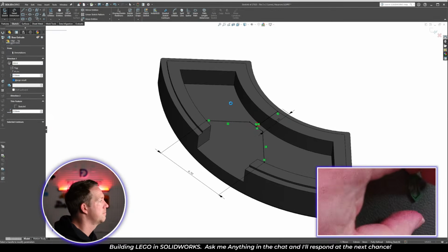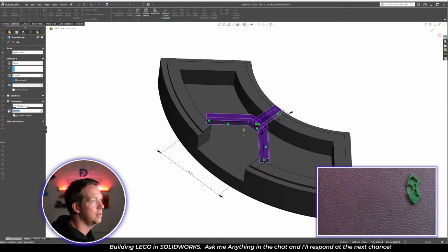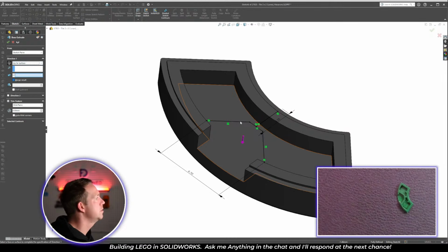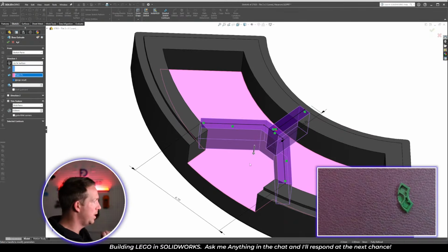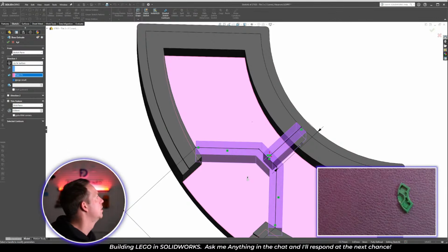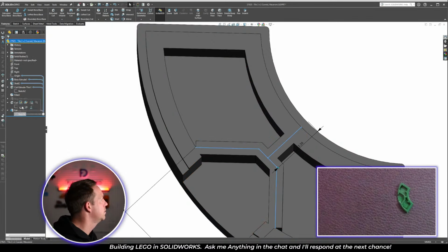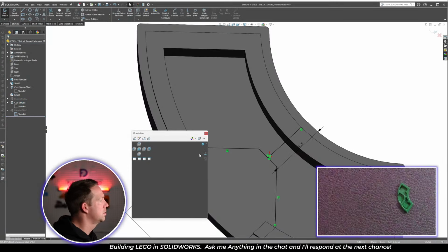So we extrude it, mid-plane, 0.8, down, going up to surface. The one thing with this, those little sketch endpoints there, I'm going to have to move those. That doesn't look right. To get them to join up properly. So I'm going to edit that sketch.